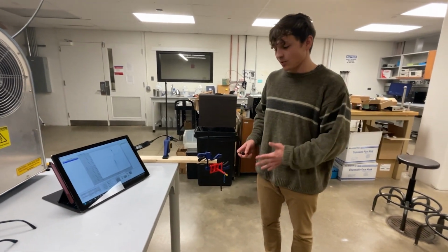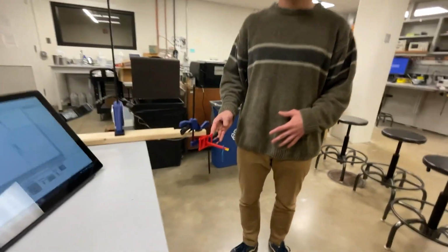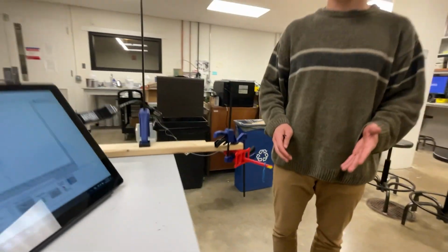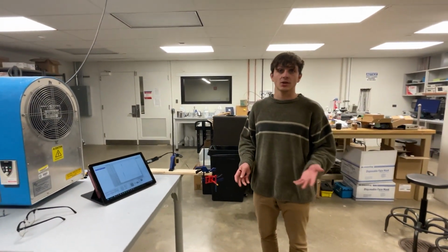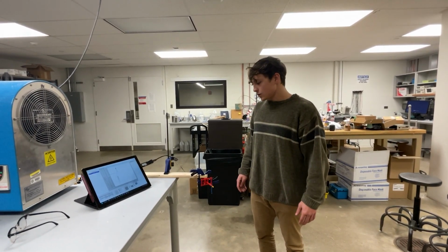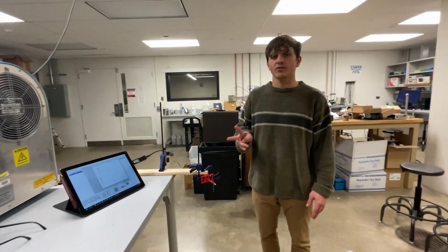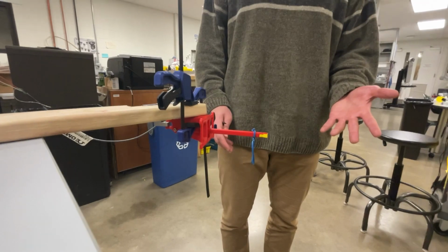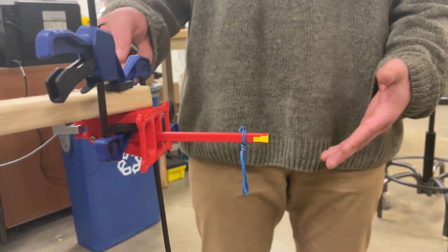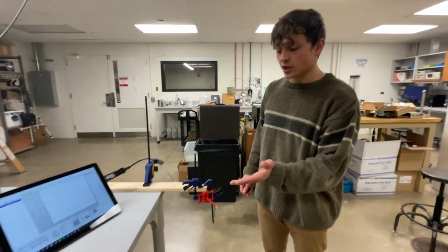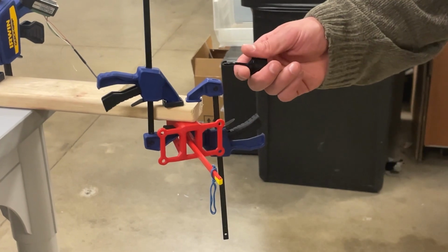So we eventually were able to get this load cell to work, which is great for us. It has good uncertainty and has a capacity of 10 kilograms, which is right around the range that we're trying to measure. To calibrate it, we actually did two different calibrations. I have one of them set up here. In the first calibration, we just applied weight directly to the load cell. And then in this setup, we actually used our force amplifying lever arm to apply load to the load cell.